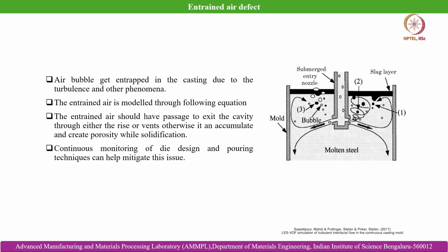Even if we do it in an inert environment, still there are some instances of some amount of gas absorption within the melt. So, we have to do appropriate degassing, that is a technique by melt processing, and moreover we also need to provide an appropriate escape avenue for the air, the bubbles which are trapped within the liquid melt.